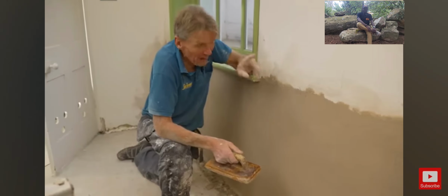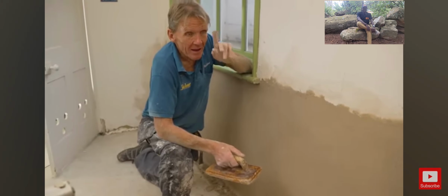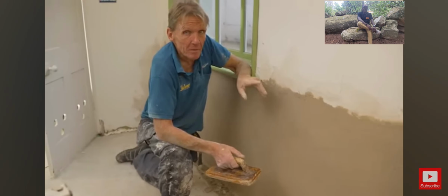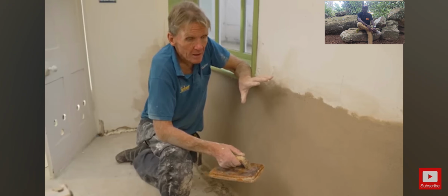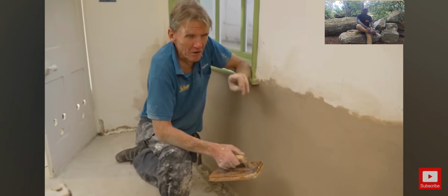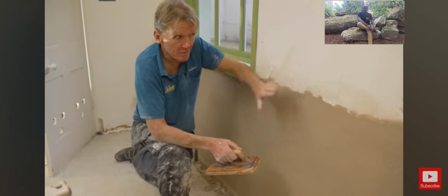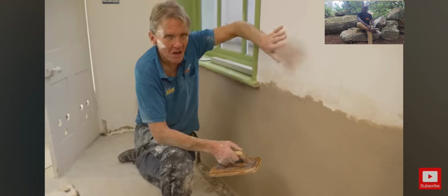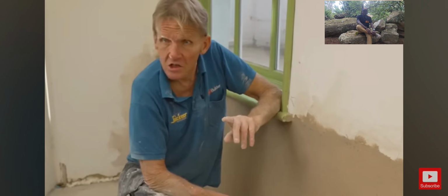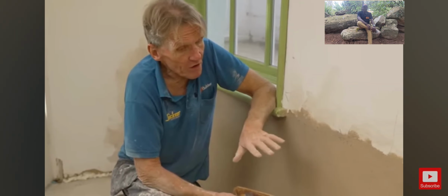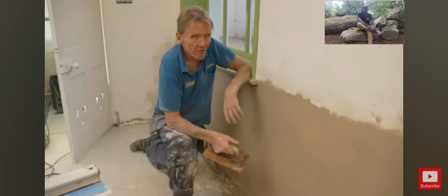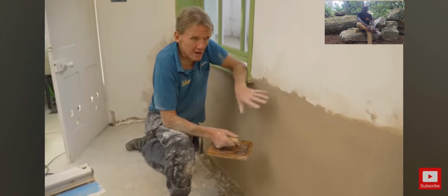But, there's always a but. 3 coats of paint, non-vinyl paint, and it will close up beautifully. And the great thing about it is that the paint will hang on here. Sometimes when you get over-polished plaster, the paint peels off. We've got cases of it in this room anyway, so I'm confident that once this is dried out, few coats of paint will close it in.